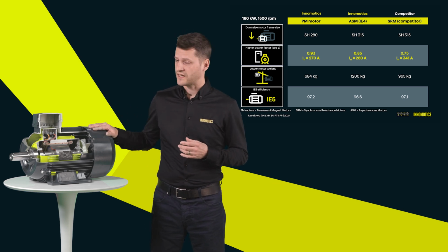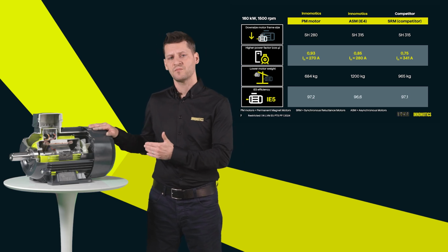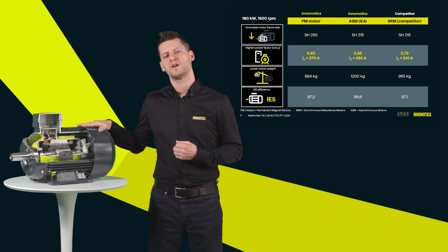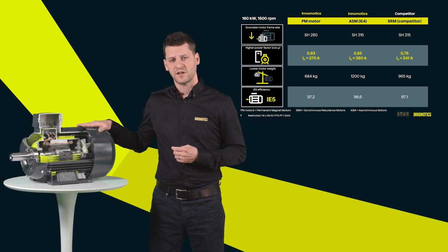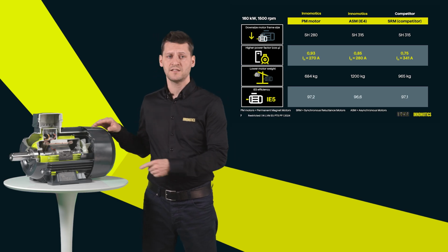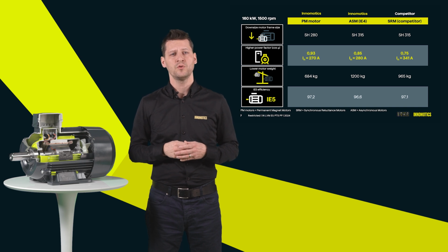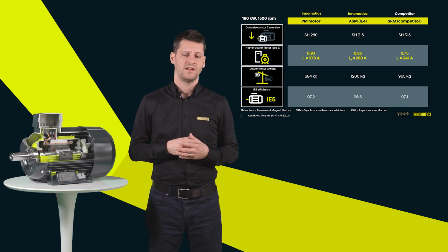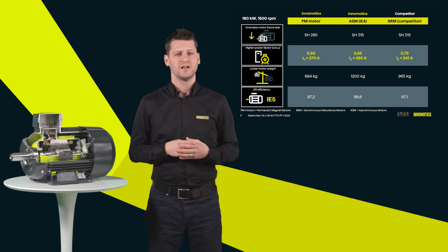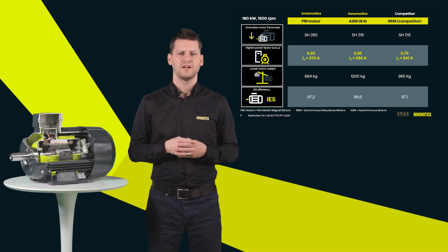Here I have also one example. This is the extreme one. We have a motor 3 shaft heights lower in the same power. This is 5.5 kilowatt. And the asynchronous motor is in shaft height 132. This motor in 5.5 kilowatt has 43 kilograms. The small shaft height 90 permanent magnet motor has only 14 kilograms. This is almost 2/3 of weight reduction. And as we already talked about efficiency as the main driver today, you can compare the values down there, and the permanent magnet motor also excels in this aspect.